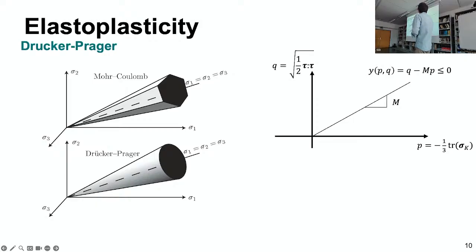Now, just to give some examples of that, if it wasn't fully clear from all the equations and text on the previous slide, you probably know the Drucker-Prager model, perhaps, which is a cone in principal stress space like this. So this is our yield function, our yield surface. It's a smooth version of the more well-known, perhaps, Mohr-Coulomb law.